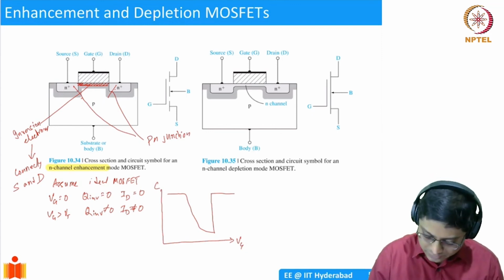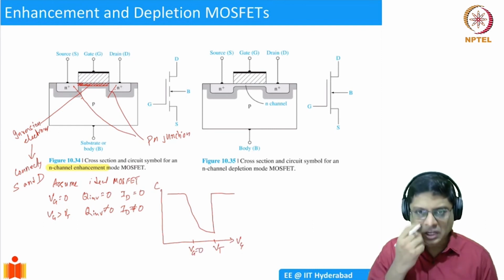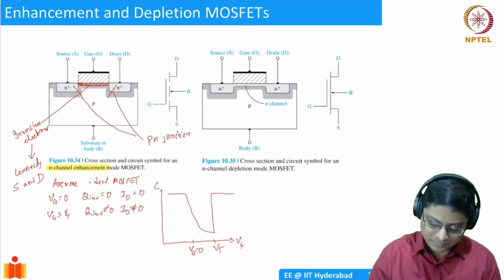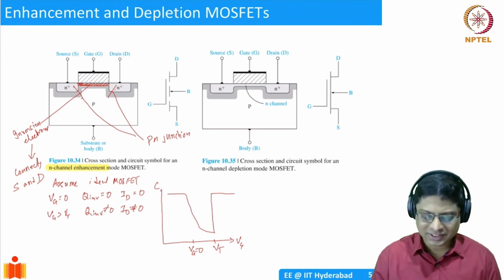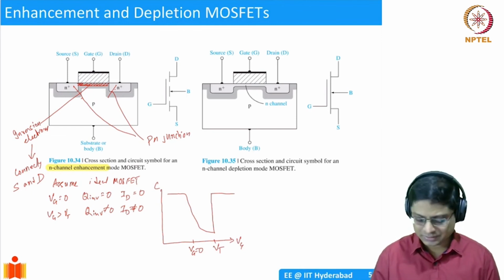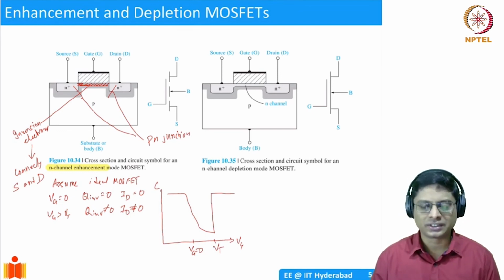And this was your VT, and this is your Vg equal to 0 volts. So now at Vg equal to 0, the device is maybe mildly depleted, but it doesn't conduct current. There's no inversion charge to conduct current, right? This is how a CV could look.